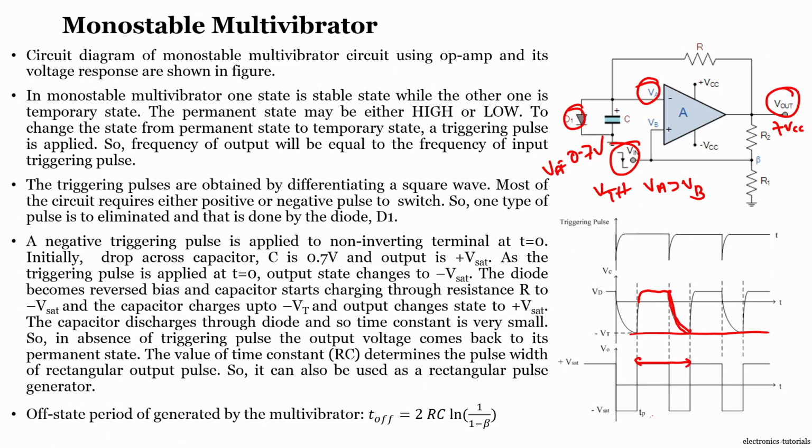the complete frequency of this signal, right. Once it reaches plus VCC, it continues the same as what we have seen for the positive cycle. So this decides the complete frequency, when to turn on and when to turn off. That entirely depends upon R and C, the charging value of a capacitor, and upon the R1 and R2 values, right.